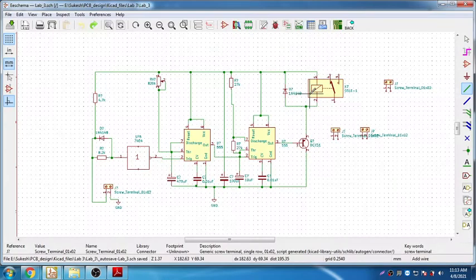So what is NC here? NC is actually normally connected, which is 4. So this is a common terminal. Pin number 1 is the common terminal which switches over between 4 and 3. So this is common and 4 is normally connected. My motor is connected to one of the terminals. Before that, let me make the connection to the VCC and all.